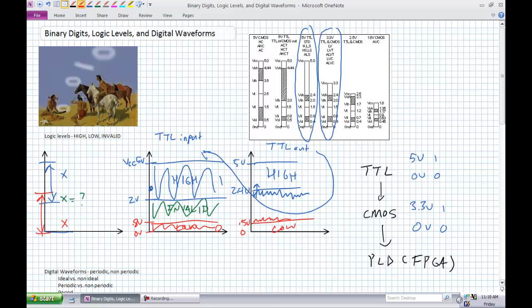One brief thing about the CMOS too, you don't always have to supply it with 3.3 volts. You can actually supply it with substantially higher voltage, provided it's capable of accepting that. I think it's up to 18 volts. I know it's 15 volts, but you might be able to supply certain CMOS circuits with up to 18 volts. But what you do is you significantly expand the region between high and low.